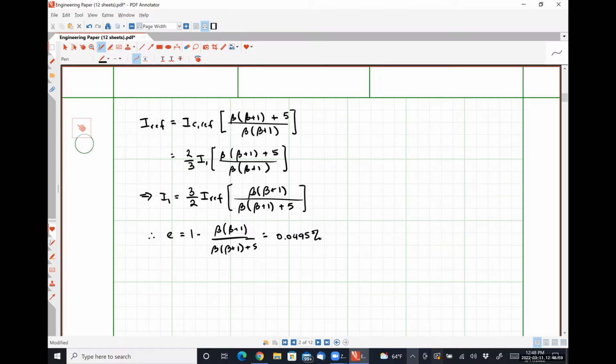So that emitter follower transistor does a lot of heavy lifting here to provide all those base currents and minimize that error. Okay, so just one additional transistor really minimizes the amount of error that we see in our current mirror scheme. Okay. Any questions about this?